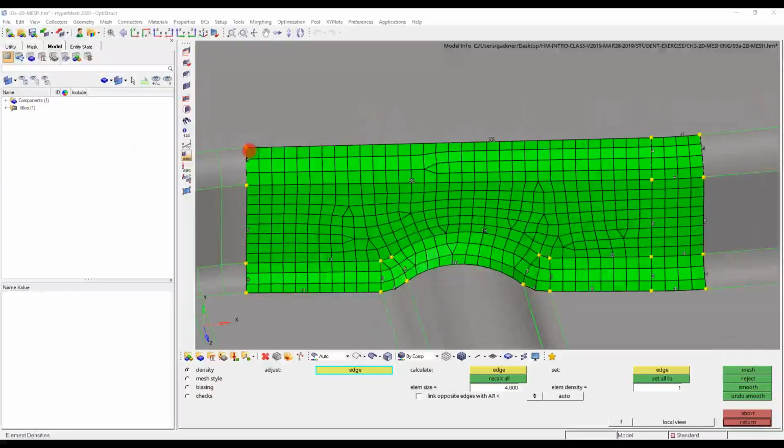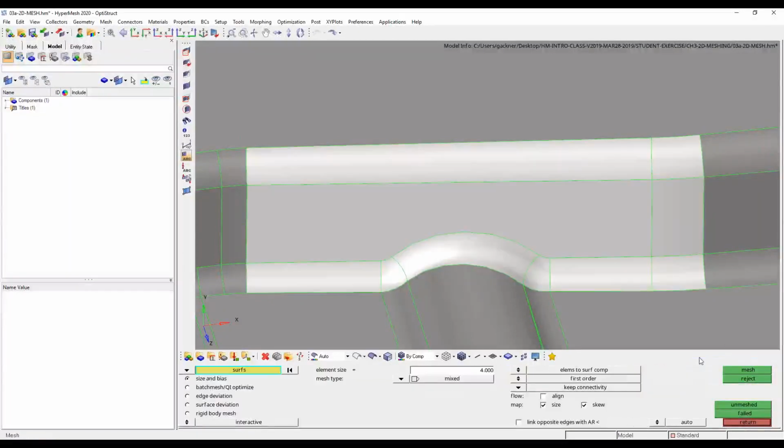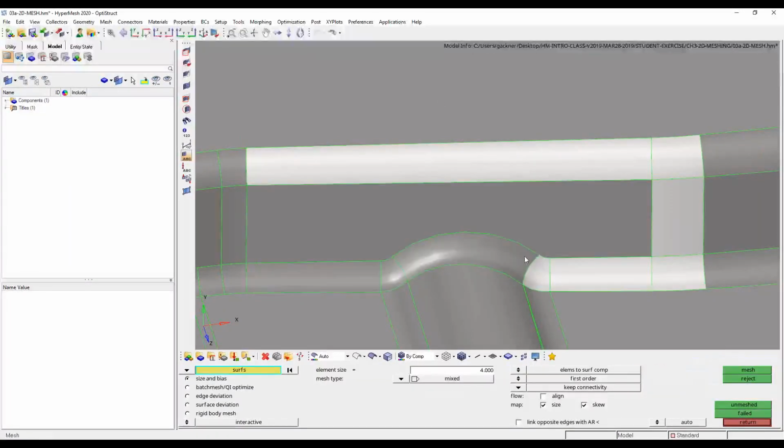Now, if we look at this top surface fillet over a couple surfaces here, I have about 4 elements along this first edge, another 32 or so that go along the long edge. And then once we get down to the more radial direction of that surface fillet, on the left side, we have 3 elements. I have 1, 2, and 3 making this up. And on the right side, I have 1, 2, 3, and 4. So let me exaggerate that a little bit here. What I'm going to do is back out of this and just mesh that surface fillet for now.